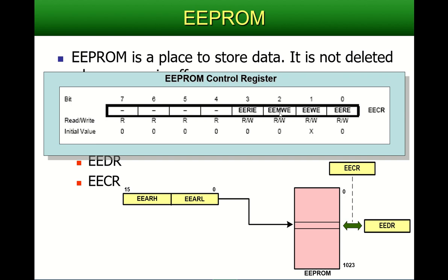So make this a 1, the master write enable. Directly after that you make this one a 1 if you want to write data into the EEPROM, and automatically it will return back to 0. And we are also going to wait. It's easy to wait for this specific bit to make sure that it is a 0, because only then can you carry on with your program.